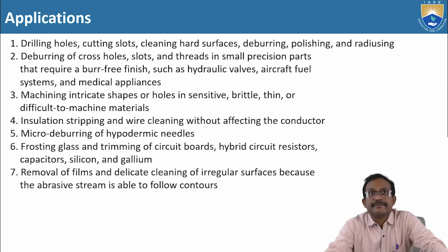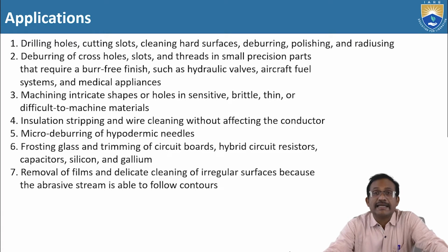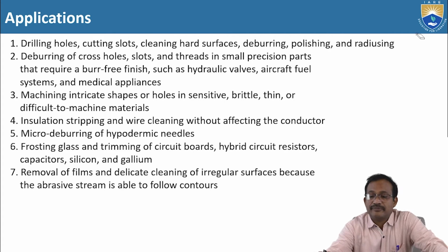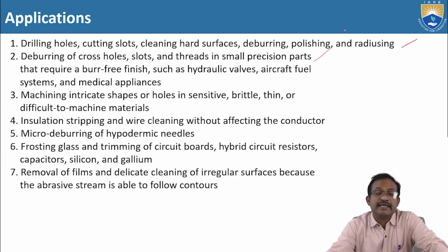Applications: drilling holes, cutting slots, cleaning hard surfaces, deburring, polishing, and radiusing are the first set of applications using abrasive jet machining. Second, deburring of cross holes, slots, and threads in small precision parts that require a burr-free finish, such as hydraulic valves, aircraft fuel systems, and medical appliances.